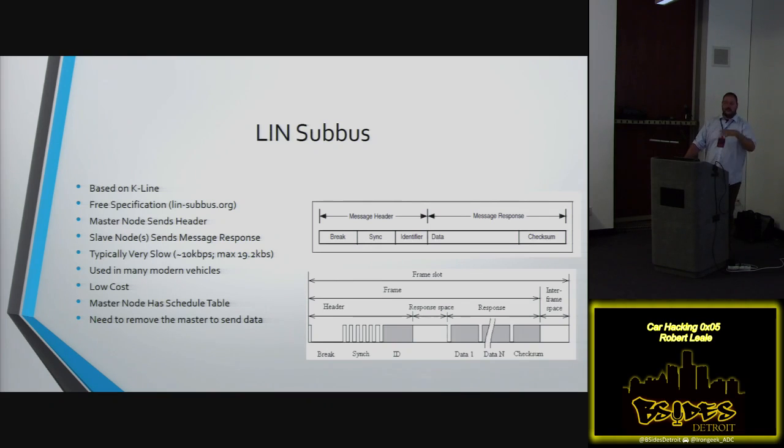But if you're trying to hack your car and have fun with it, if you want to, maybe turn individual lights on, or get switches, a lot of those little switches, like your driver door window switches and things like that. If you want to do controls, they're typically going to be over LIN bus. I have some customers that use LIN bus for turning the windshield wipers on. If you want to turn the windshield wipers on, LIN bus is a really good way to just activate those features effectively. So LIN bus is kind of unique.